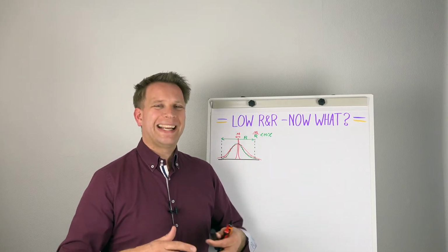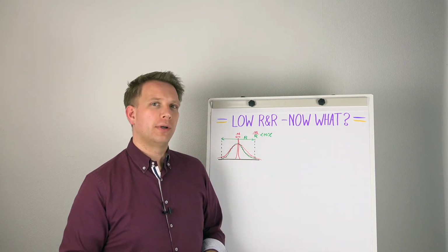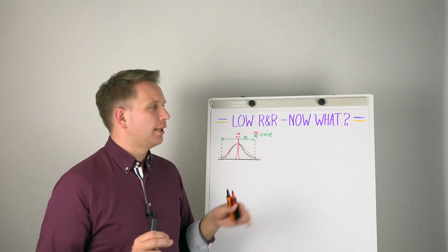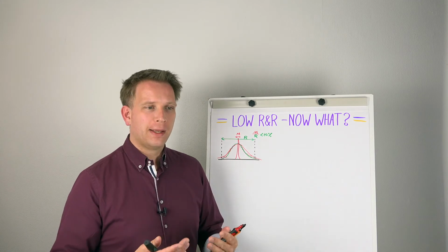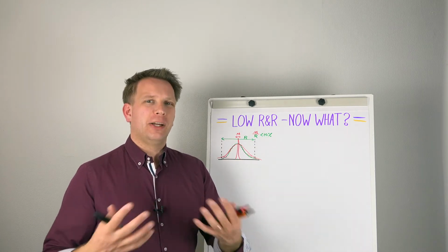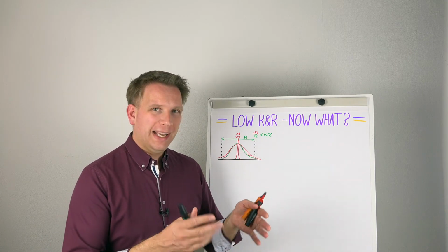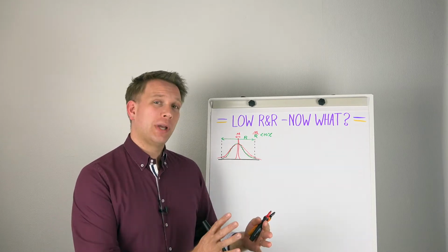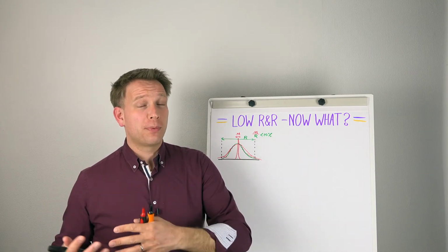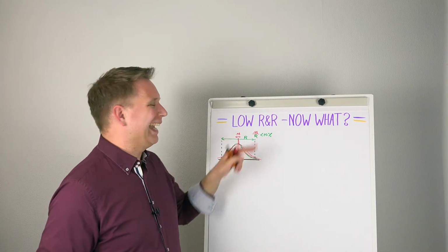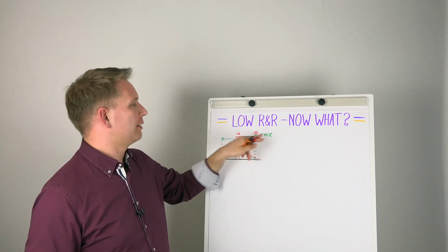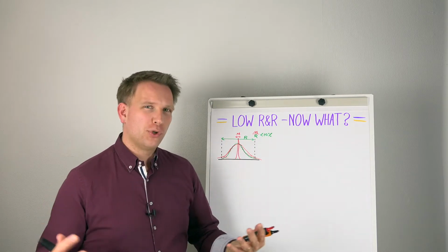Do you just want to get a broad insight and just know where your product is going? Then it's all fine. Do you really want to use it to upgrade performance or to make changes in your system? That is, are you doing the type of Six Sigma work where you are looking at parameters, changing them a bit, then looking at the result in the product, and based on that you want to decide which parameters are best? Then you really need to get a measurement system that is a lot less, or at least less than 10% of your spec or observed range.